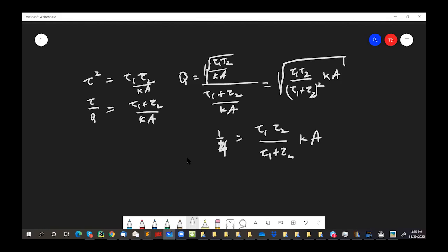Okay, now I'm going to make an approximation, and this is the trick to make it solvable easily, is just to say that I already know that tau 2 is going to be much, much less than tau 1 for this to be true. I know I have to make the amplifier fast, right? So I could just cancel this part.